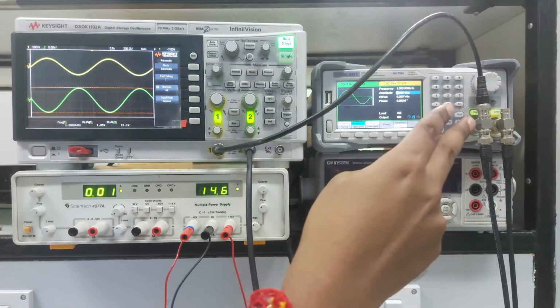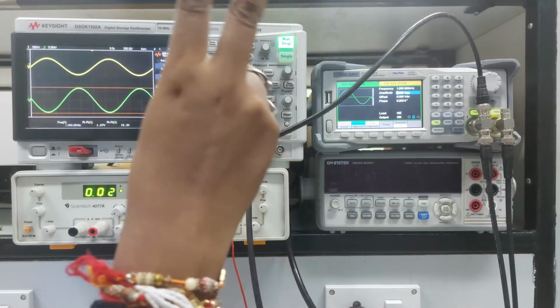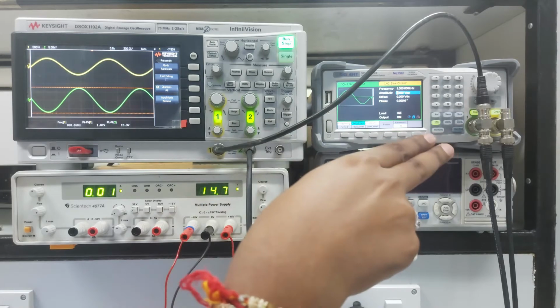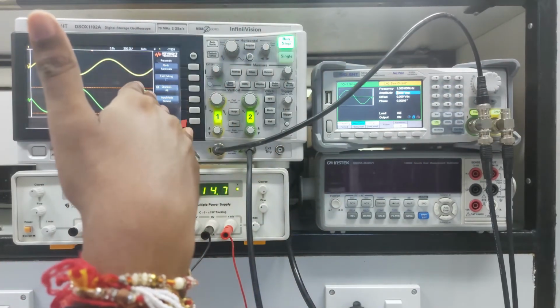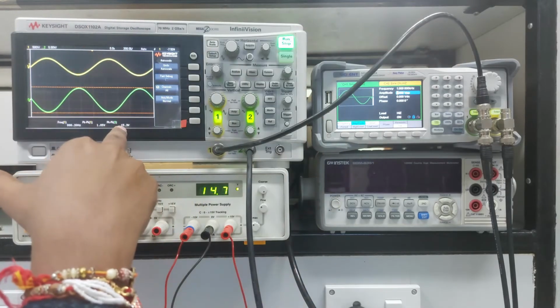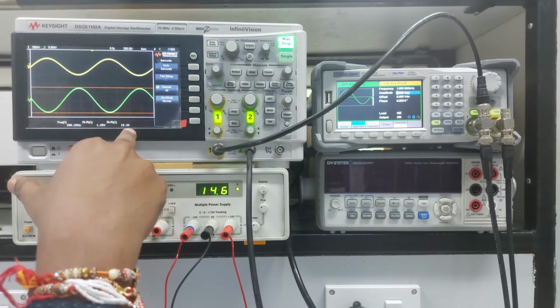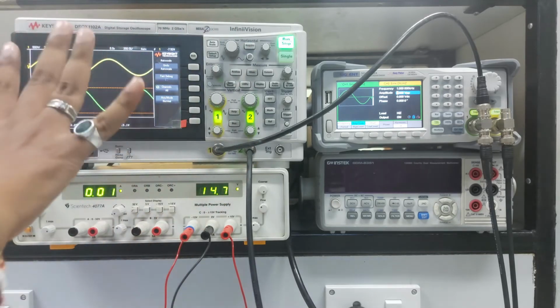From the channel 1 we are giving 1 volt, from the channel 2 we are giving 0.5 volt. So they are summed up, that means the op-amp will sum up these two inputs, 1 volt plus 0.5 volt, and it will multiply by the gain, that is 10. So 1 plus 0.5, that is 1.5 into 10, and the inverted output is amplified by 10 times. Now it becomes 15 volt. So that is the thing, it is adding actually.